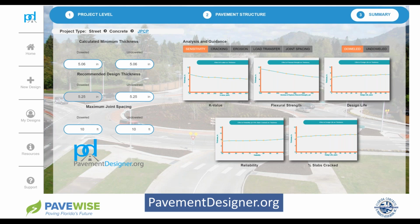But we recommend the design thickness. We go to the next higher or next thicker 1/4 inch. So basically, it's doweled or undoweled, 5.25 inches thick, and the joint spacing is 10 feet. And what Amy likes, she likes these sensitivity analysis and guidance things over here on the right-hand side. And I'm going to show you why.